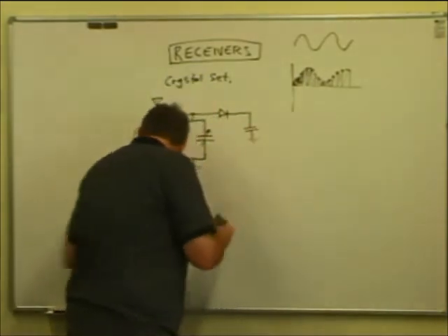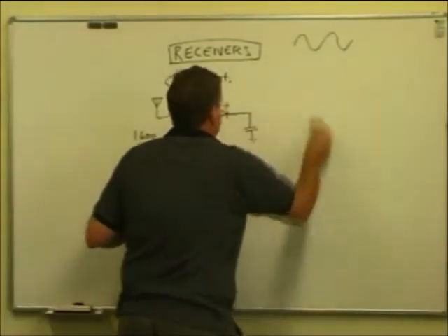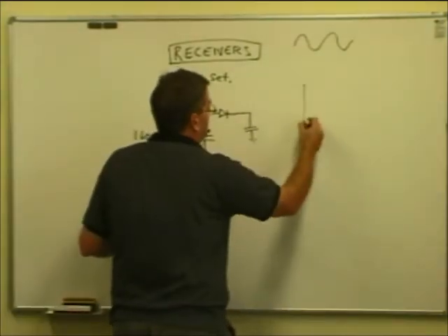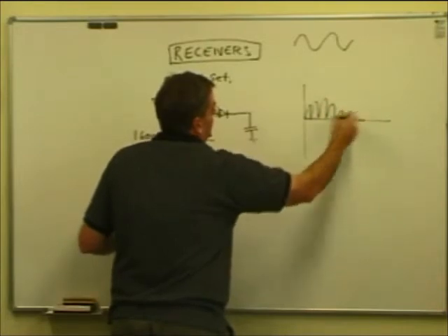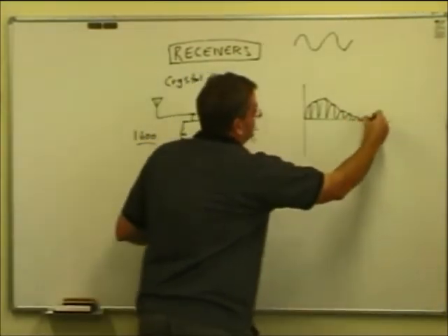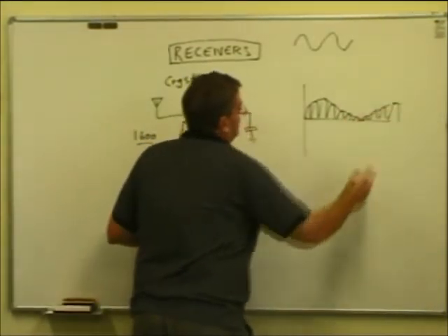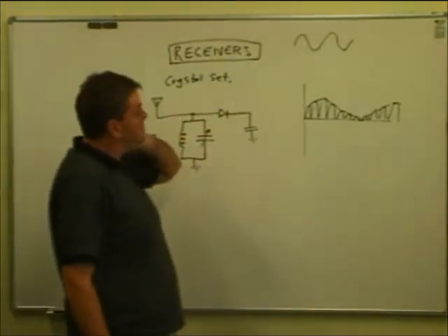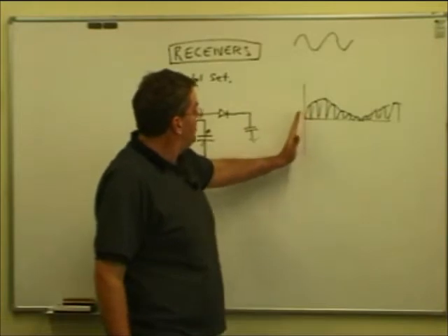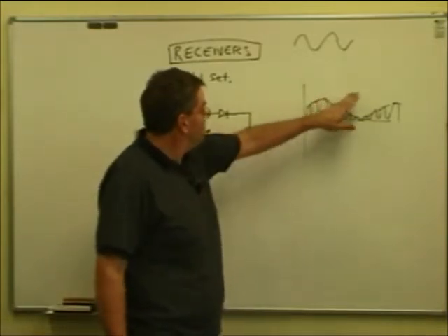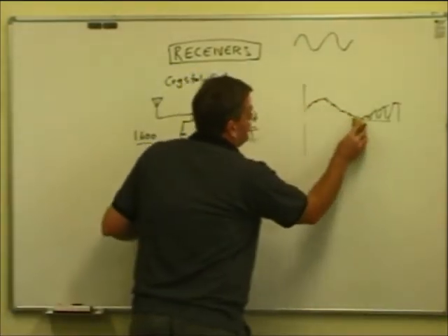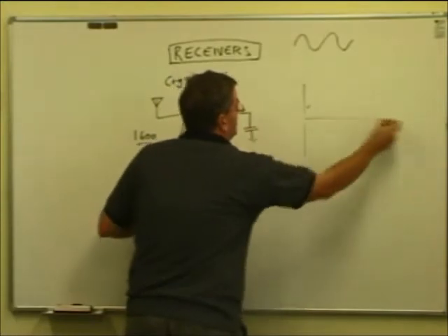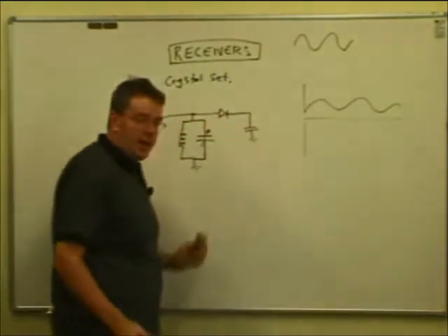So, right, my pen's falling apart here. So that's the carrier there. We get this effect here. So we recreate our audio signal, if you like, off the AM signal. We remove the other half, and what we've done with the carrier, the capacitor can just charge up between bursts of carrier, and then we end up with, another thing it's doing is filtering off the carrier wave. Redraw it. We end up with this, our original audio signal.